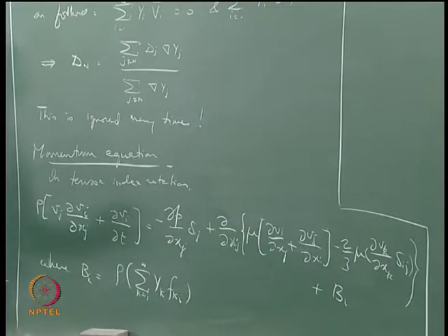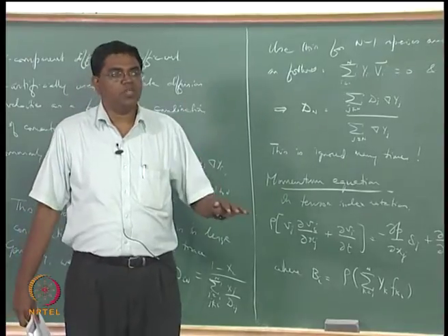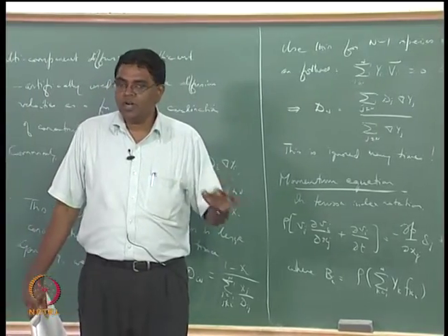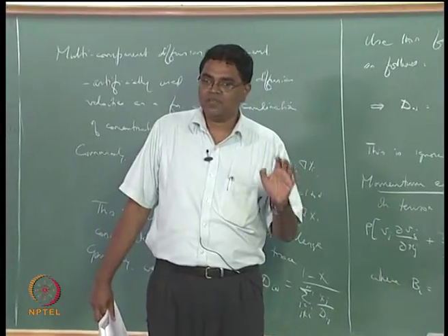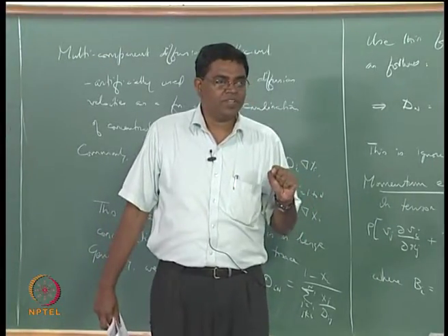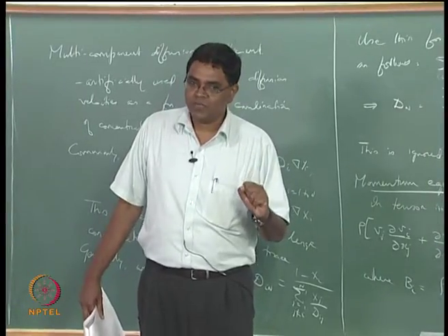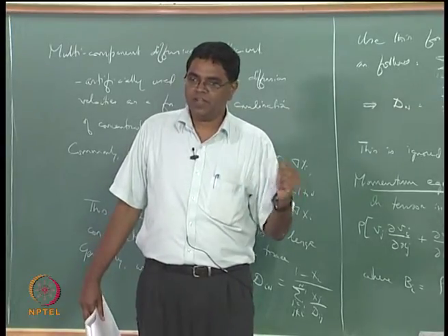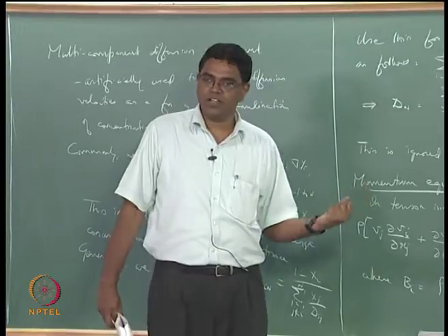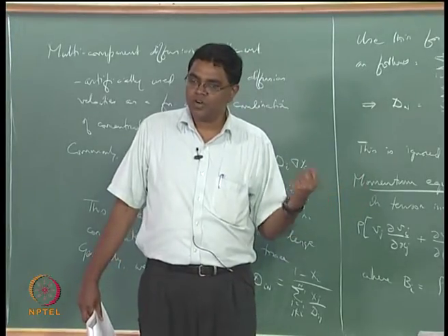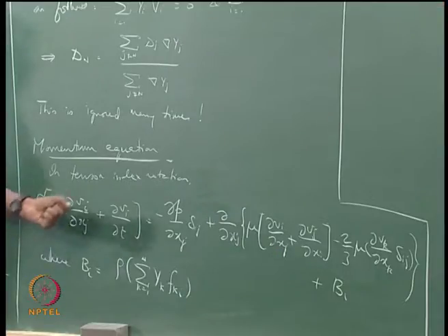This is the reason why in many PhD qualifying exams people may ask you something that you learnt in your undergraduate fluid mechanics. Is Bernoulli's equation a statement of energy conservation or is it a statement of momentum conservation? The answer is both, right? You could conserve momentum or you could conserve mechanical energy. It is a matter of just taking a dot product of the momentum equation to get your mechanical energy. So in other words, if you are conserving momentum, it amounts to conserving mechanical energy. What it does not do is conserve the thermal energy.